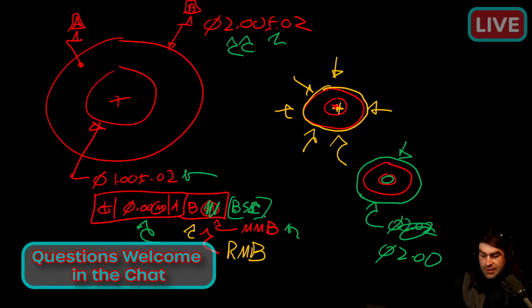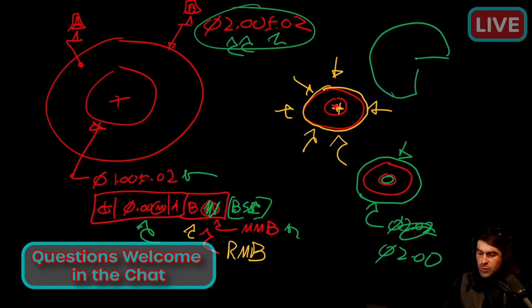I got to go back and look, and I don't think there's anything that says it has to be a basic dimension. Maybe there is. I'll post a correction if I'm wrong here. I'm just trying to find the example they give in the ASME standard, which is like this weird Pac-Man looking thing where they're controlling a non-opposed surface with profile.